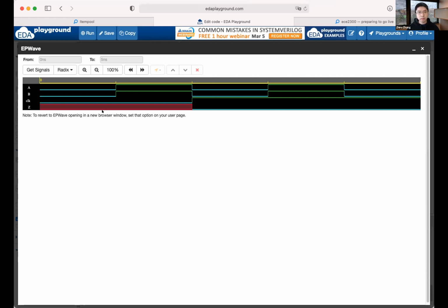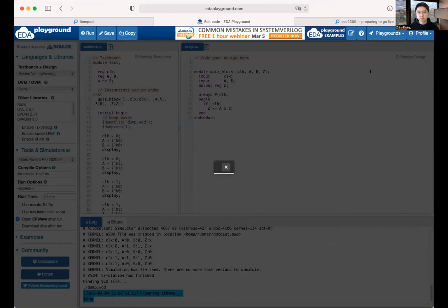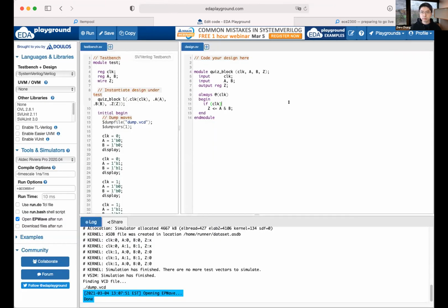although clock is high over here, see this waveform, clock is high, and A and B are changing. Somehow Z is still stuck at 0. This is also not a latch for some reason. Agree? So right now, this is not behaving like a latch. So what's going on? How do you fix this code?